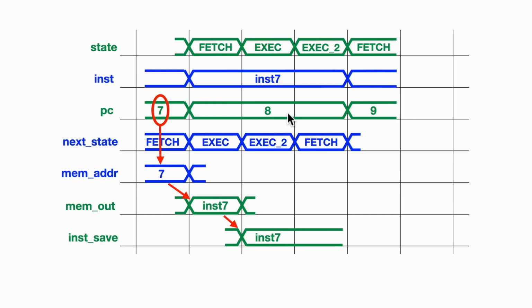For some instructions like call and return, we'll be loading it with something different, but that's typically what happens. And then on the clock edge, when the instruction starts, we'll be loading it from a previous value and thereby incrementing it. So we see it being incremented, and this is what it looks like for normal sequential execution.